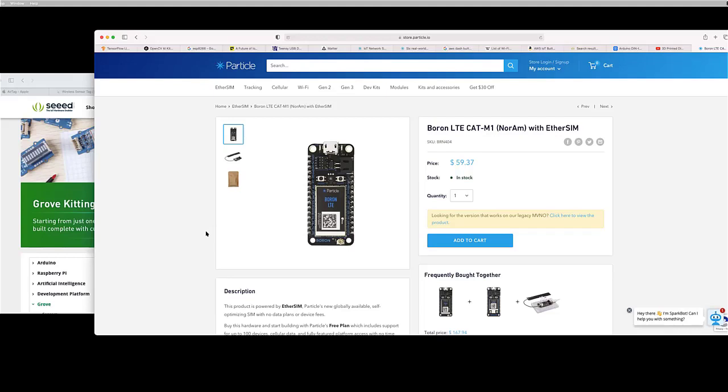OEE can be valuable. OEE can be long-term, like what's the OEE for the whole year? And in that case, you'd probably want a permanent installation. But a lot of people aren't collecting that metric to begin with. And if you're not collecting that metric, get OEE for a day, OEE for a week, OEE for a month. Those are all well within being able to use a battery powered sensor on a machine 24/7 for several days to get that OEE calculation.